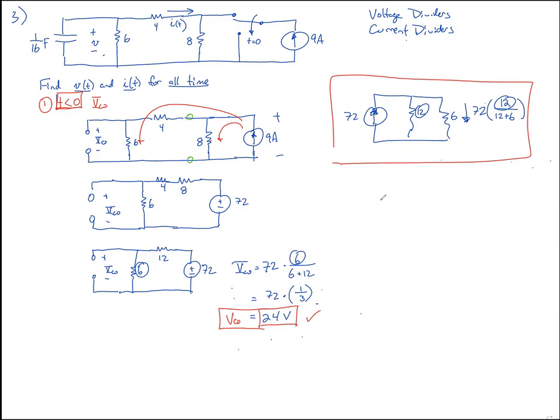If there's an inductor in the circuit, the only thing you find is the current through that inductor, and then you're done. And the reason why you find that is that if you know this is the voltage across the capacitor for time less than 0, then that's got to be the same as the voltage across the capacitor for time equals 0, even after the switch is flipped. Because at time equals 0, there's no current flowing through the circuit.